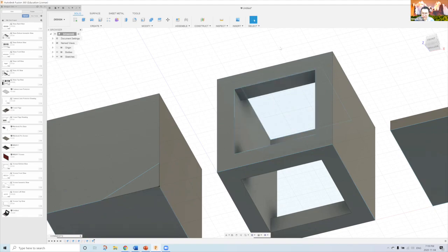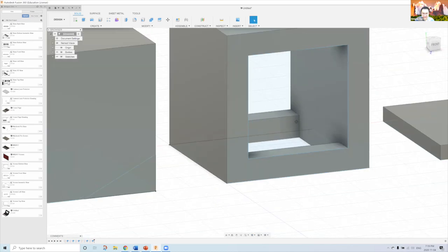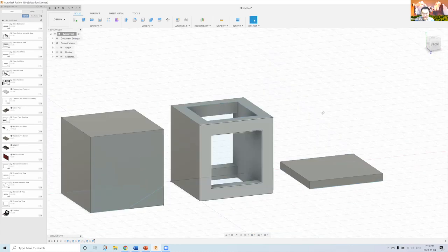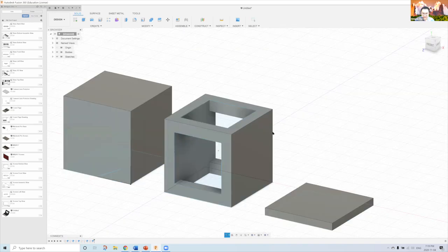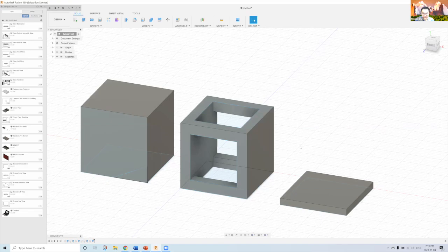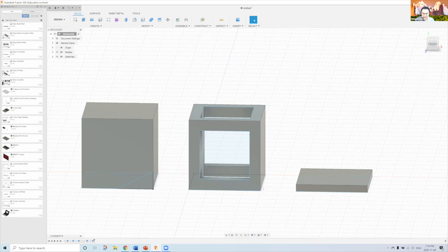So what you will have to do in this case is reorient the model to print better, or implement supports. So here is how you can orient the model better. What you could do is turn this entire thing 45 degrees, if you want to turn this over to have it stand on, let's say, one point out of the six, or out of the eight, sorry.